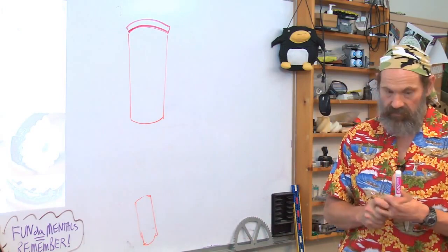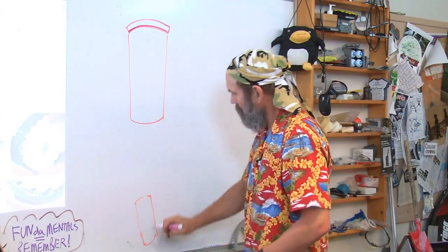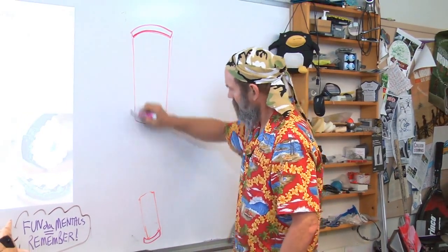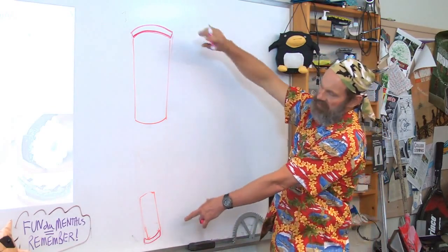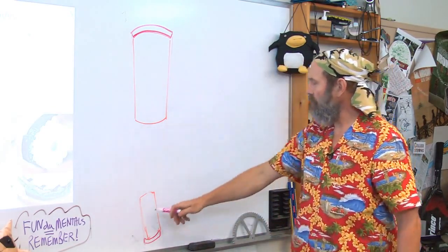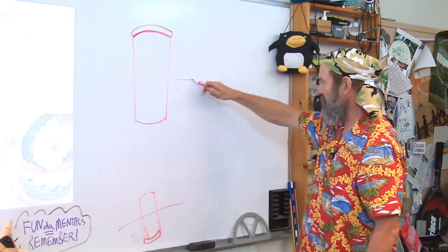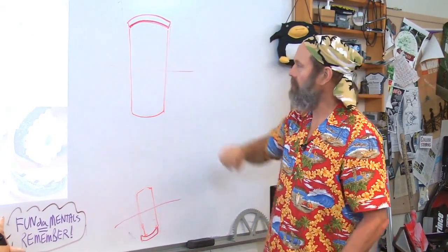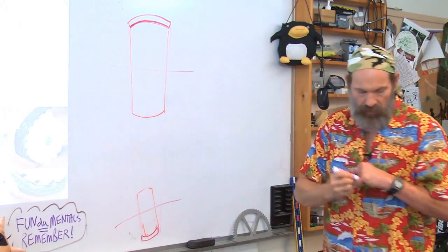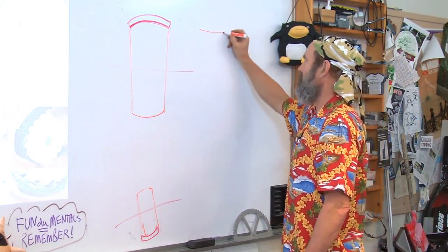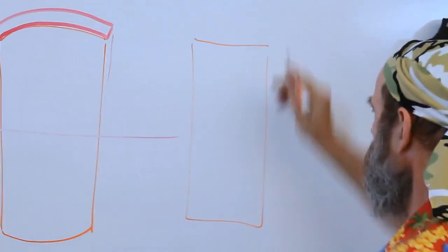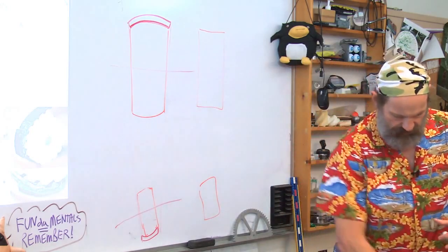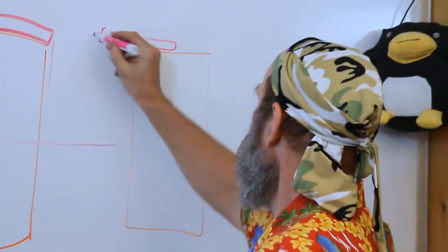the belt will not, this is a flat belt. Imagine this is perspective. This one's far away. It looks smaller. Even though these shafts are misaligned by up to a few degrees, this belt will not come off the shaft or the pulley. It'll stay on. If, on the other hand, the pulley was flat, and anybody who's used a belt sander will know this, any misalignment, like fractions of a degree, and the belt walks off. Whee! Takes off.